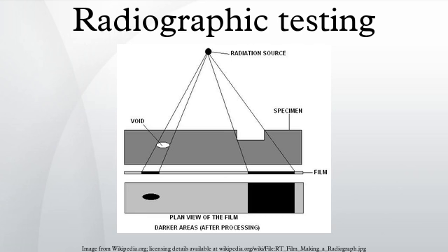ASTM E592, Standard Guide to Obtainable ASTM Equivalent Penetrameter Sensitivity for Radiography of Steel Plates 1/4 to 2 inches, 6 to 51 mm thick with X-rays and 1 to 6 inches, 25 to 152 mm thick with cobalt 60. ASTM E747, Standard Practice for Design, Manufacture and Material Grouping Classification of Wire Image Quality Indicators used for Radiology.